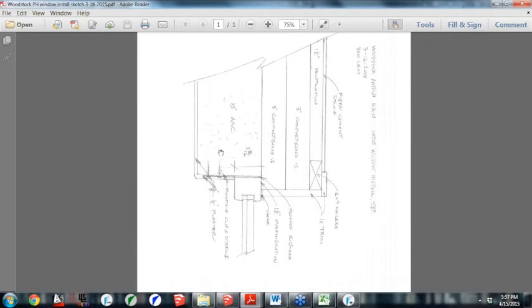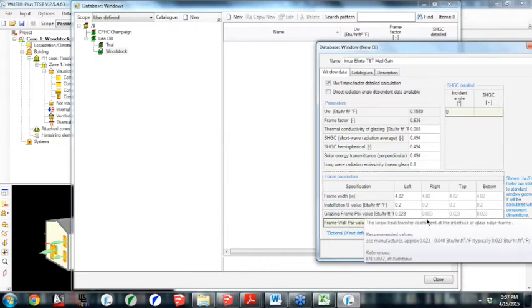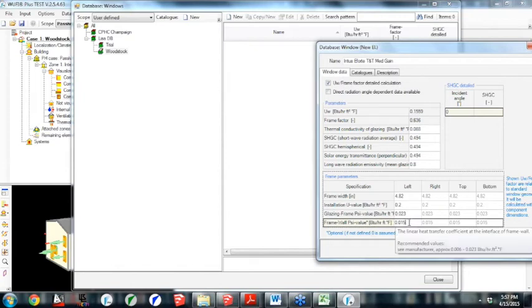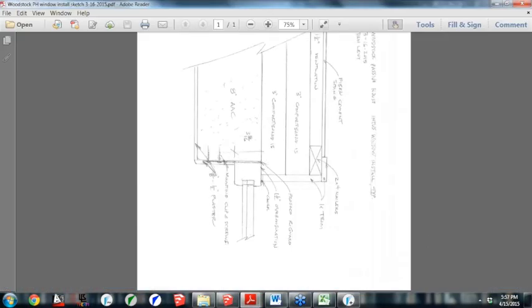Because of that, we will input a median value for the frame wall psi value. I guess it's actually a low value in terms of certification. In our certification guide, you'll see that there's a couple of values that, based on experience and different calculations of the installation conditions, we will let you input down to 0.015 for the psi install if your window is installed in the middle of the wall and has over insulation. So this project did both. So that's great. And that's the value we'll use. So I'm going to keep that open actually.